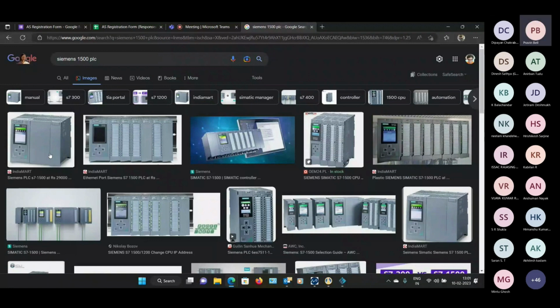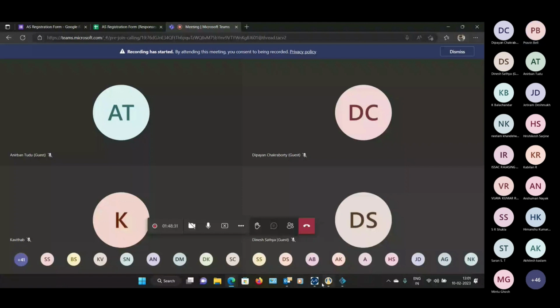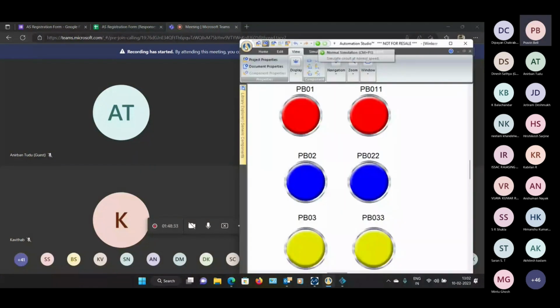So what I mean is that if you plug a TCP/IP cable into the Ethernet port of this 1500 series PLC and connect it to my laptop, I will be able to read the data tags directly from the hardware. So there was one question by Dr. Sir sometime back: can I communicate? Yes, through OPC connectivity, I can communicate like this. The data speeds will be between 1 millisecond to 10 milliseconds. So this is available in the 1500 series. So that is the OPC backbone.